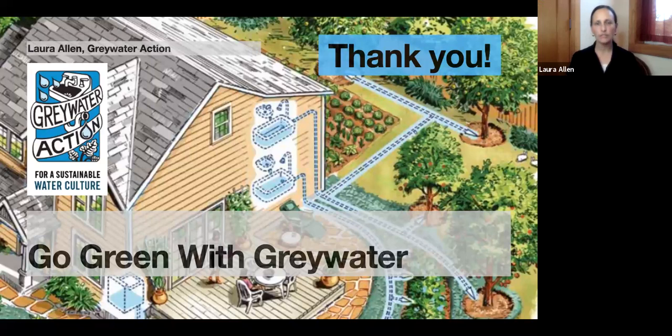So typically gray water from a home, if you have a septic, goes and soaks down into the ground on your property. So it does stay local. But if you're on a sewer system, it leaves your property, it goes with the black water, the toilet water, and mixes into all your neighbors and all the businesses. And now it all goes to the wastewater treatment plant where it's cleaned, nutrients are removed, it's disinfected to kill germs, and then it's dumped out in the nearest waterway. It's usually a river or some kind of waterway nearby. So depending on where you live, you can find out where it goes.